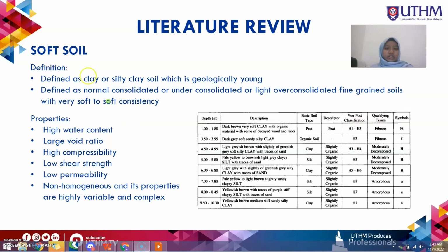For the literature review, soft soil is defined as clay or silty clay soil which is geologically young. Soft soil is also defined as normally consolidated, under-consolidated or lightly over-consolidated fine-grained soils with very soft consistency. The properties of soft soil are high water content, large void ratio, high compressibility, low shear strength and permeability, and it is non-homogeneous, with properties that are highly variable and complex.